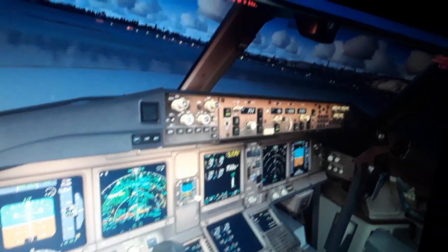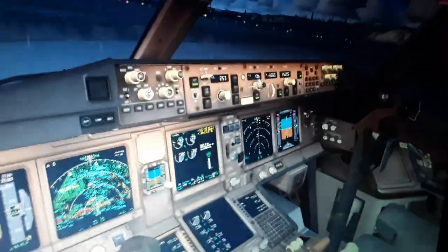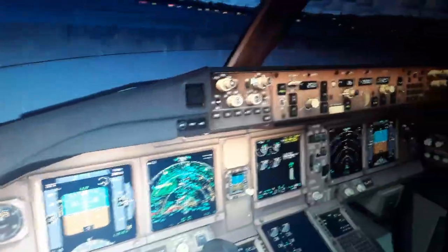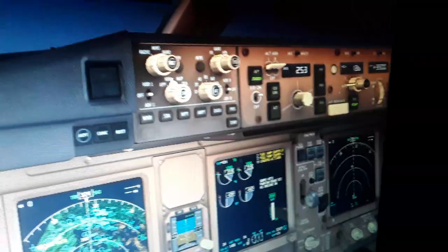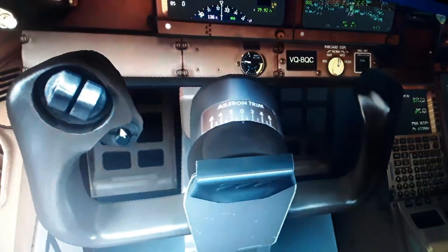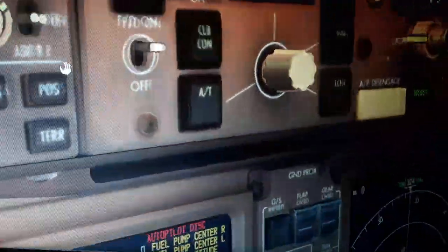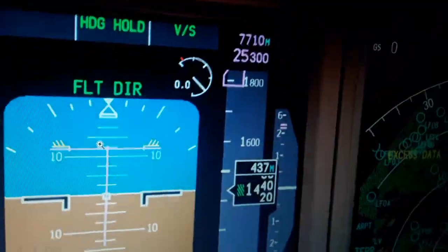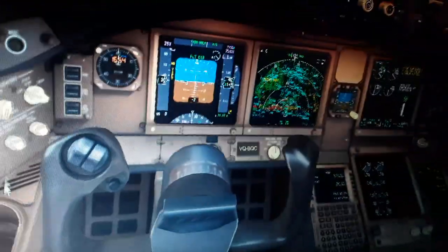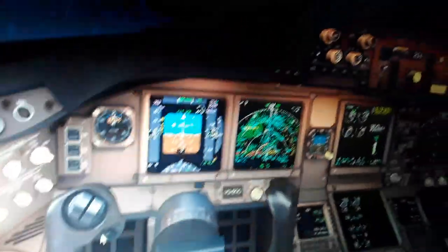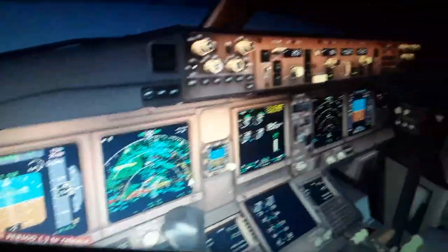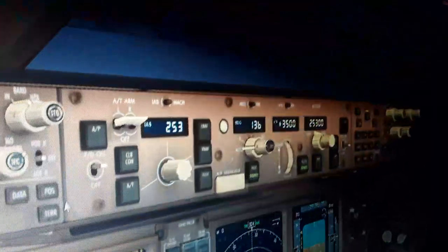So we have less than 1 hour now left. So I will continue. I will show you again how this disengages the autopilot. I have to show you this. Press this switch in the handle of this control wheel. You will see the indication again. This is the autopilot disconnected, and the flight director here is on the green light also. So you cancel one more time, you press, and it confirms the autopilot disconnect.